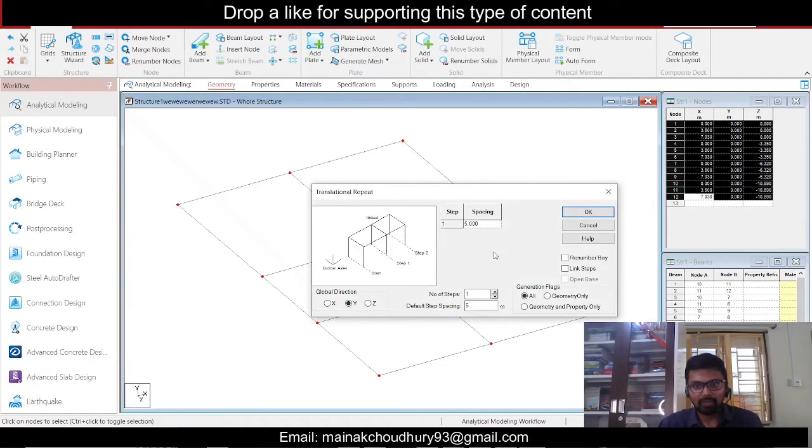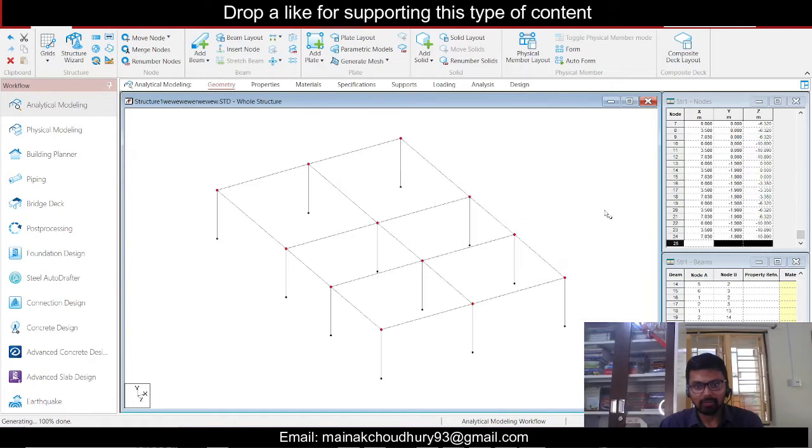In the y direction, the spacing will be negative. Let's take minus 1.9: 1.5 for the foundation and 0.4 for the plinth. Let's take this value, use the link steps option and just click on OK. So this is the foundation level and this is the plinth level.